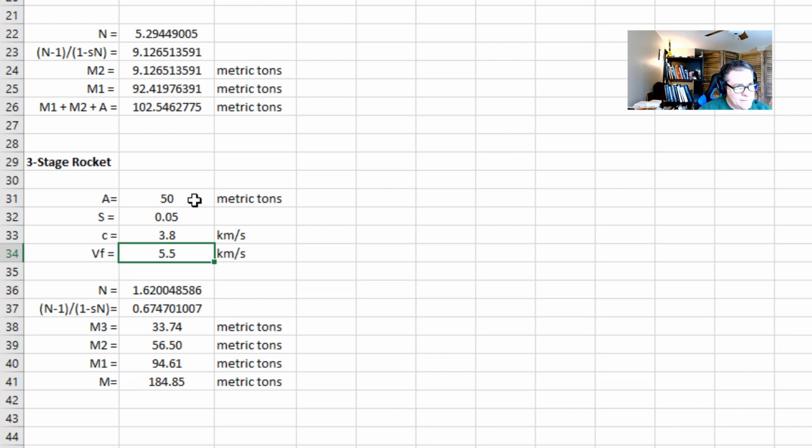And for the final delta V that we need to actually not only get into orbit around Earth, but then get on the way to the moon, we will increase this to 14. So here are my theoretical results. 3rd stage, about 146 metric tons. 2nd stage, about 570 metric tons. 1st stage, about 2,200 metric tons, making the whole thing about 2,942 metric tons, 2.9 million kilograms, roughly, for a payload of 50 metric tons, or 50,000 kilograms.